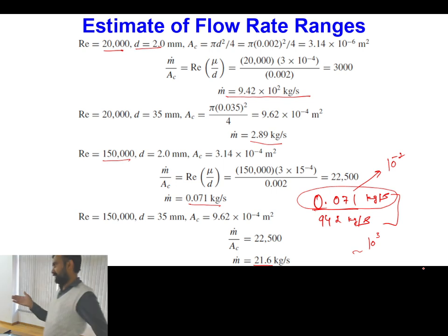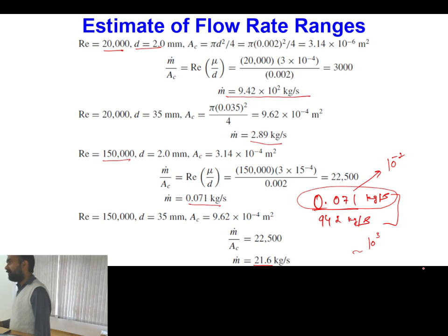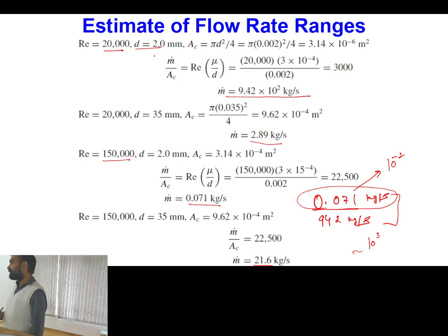And of course, in that scenario, once we have proposed some correlation, in order to test that for other tube diameters, we may have to repeat experiment for one more tube diameter. Is this point clear? Because ultimately, if you try to consider the entire range, then there is no limit. You may have to take 2 mm, 2.5 mm, say 3 mm. So likewise, the number of diameters which you have to test will become huge.